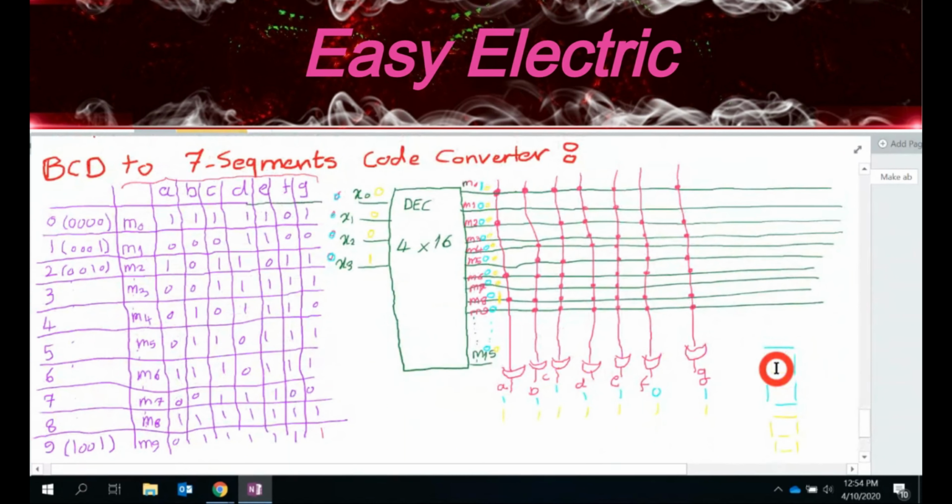So if you want to do some extra work if you back to the whole labs that you did, especially for adder and subtractor, right now you could add a 7 segment in your inputs, which is whenever you give 4 bits input, it shows what that input is, right? And also use the 7 segment in output.